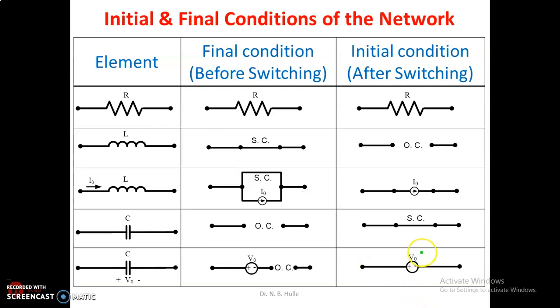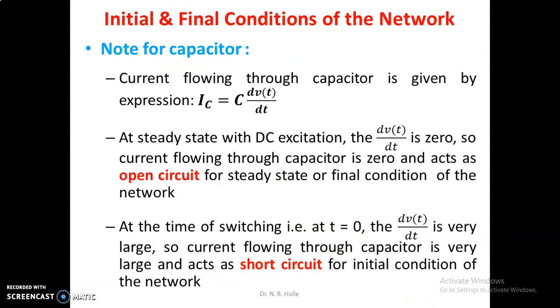Now I will come to the discussion of the capacitor. Here, during the final condition, the capacitor acts as an open circuit, and during the initial condition, the capacitor acts as a short circuit. I will discuss its explanation and then I will come back to this slide.